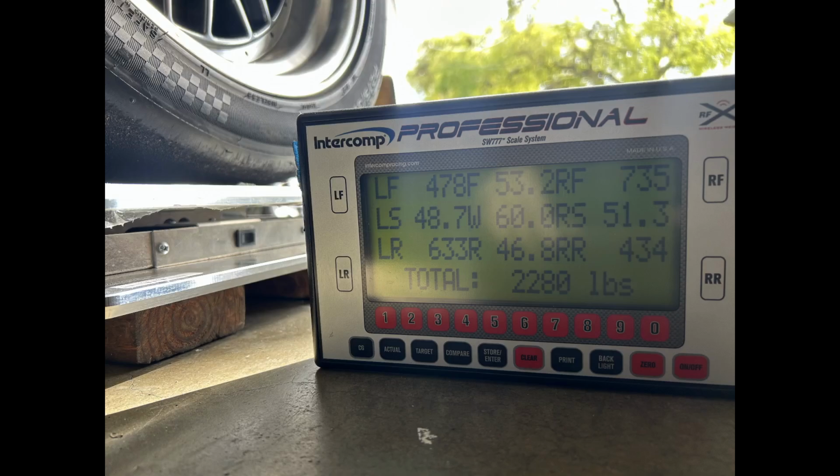I happen to have a set of automotive corner scales, which allow me to measure the weight at each tire while my race car is at rest, with or without me in the driver's seat. This at-rest data is used to parameterize the HyperMu vehicle model. Then I can mimic a real shaker rig by raising each corner scale by a known distance and measuring the corresponding change in weight distribution.